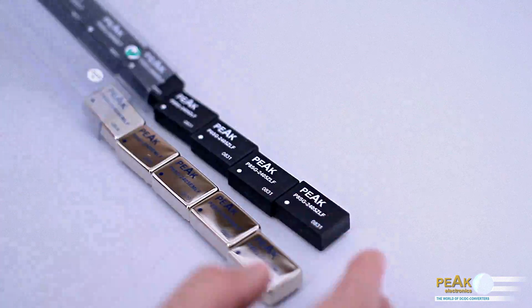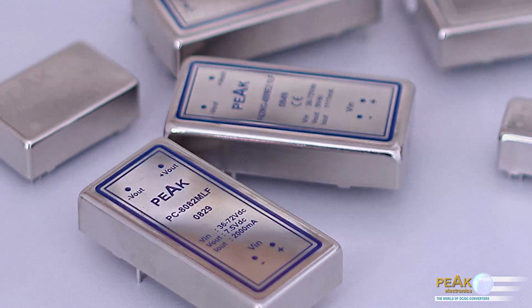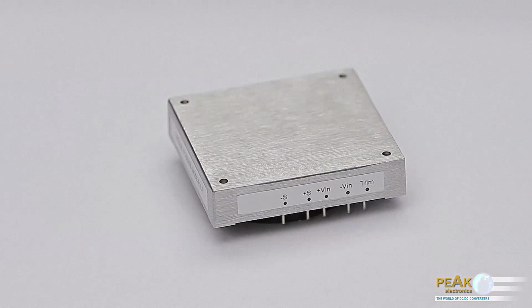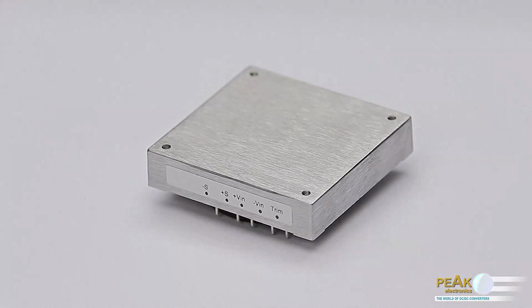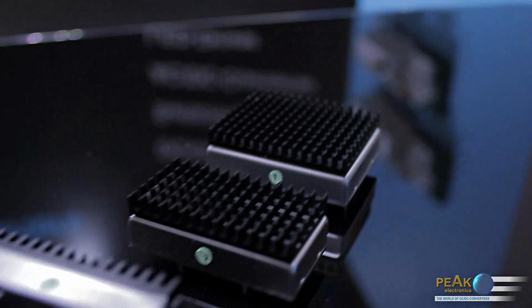DIL 24 packages, approximately 1.5 watt, 1 inch by 2 inch packages up to 2.5 watt, 1.6 inch by 2 inch packages up to 3 watt, and 2 inch by 2 inch packages up to 4 watt. These values are based on a maximum ambient temperature up to 50 degrees centigrade. When making the first calculation, if higher power loss values or higher ambient temperatures are expected, some leeway should be left for improved cooling solutions.